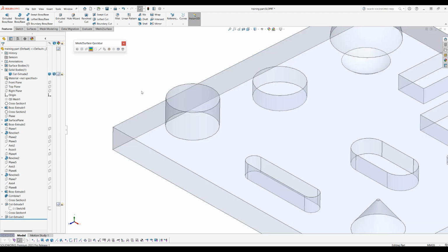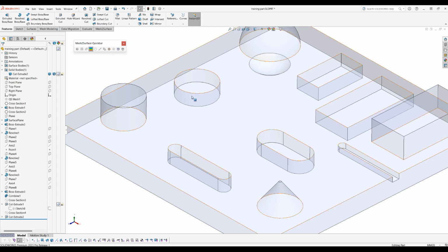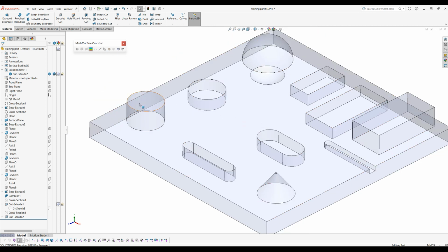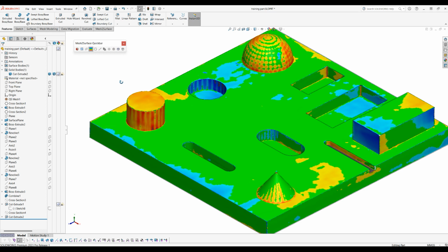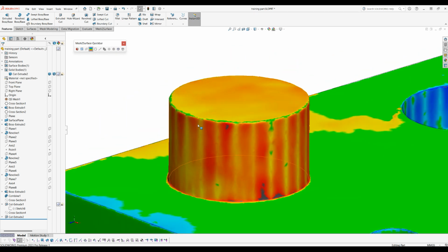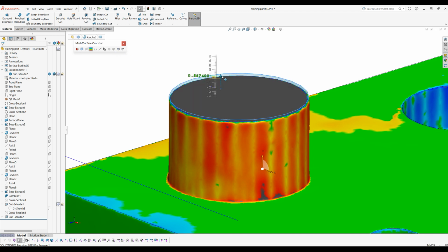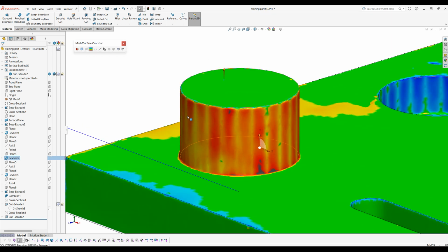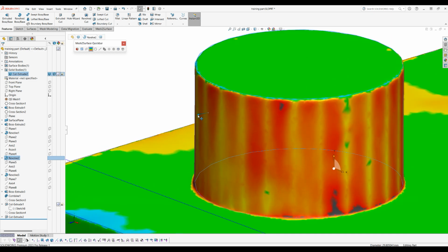This means that the object looks something like this. The main idea is that because the object is drawn transparent, now you can easily see the underlying mesh. I will just show the mesh so you can see it on the screen. Now, because instant compare is enabled, I will pick this face on the top and start dragging it. What you can see instantly is that Mesh2Surface for SolidWorks automatically applies compare so you can find the better position of your extrusion. The same applies if I change the radius of this cylinder.